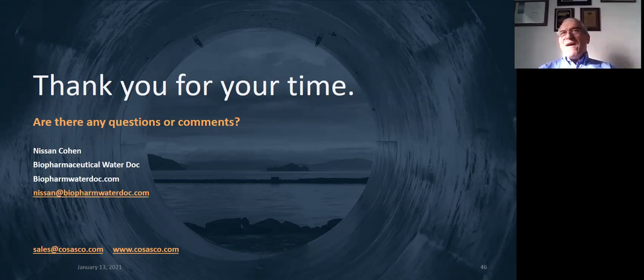It's below a half of a micron, and it's achievable over time. But you can set it up for whatever value you think is indicative of your water system, whether it be 400 nanometers, 500 nanometers, 300 nanometers. It could be even higher, as high as 1 micron, but it needs to be a number that is going to be assignable both by you and your QA/QC department.